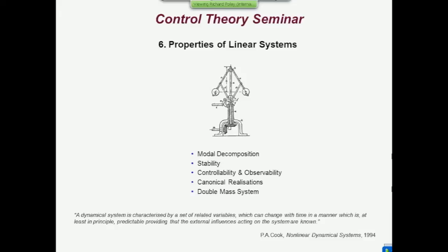Those are called controllability and observability. They don't apply to the transfer function description, but they do apply to the state space description. And they're very important because when we later go on to design control systems using the state space paradigm, if the system is not controllable, our effort will be futile. And then still later, when we go on to design an estimator or an observer, it's the same thing. If the system we begin with is not observable, similarly, our efforts will be futile. We can't estimate the states from an unobservable system. So controllability and observability are important properties that we'll need later.